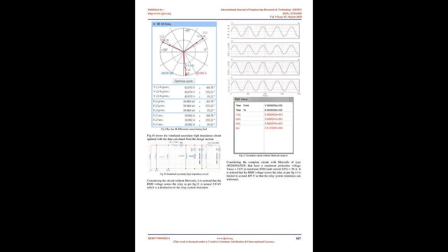So in our case Vmax equals 4.7 kV, VRMS equals 3.3 kV, equals 12 mA. Then from the Metrosil manufacturer data sheet we can select the suitable model as per Table 2. Table 2. Metrosils model selection.